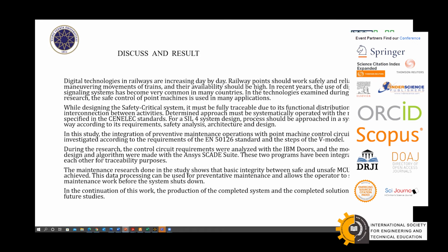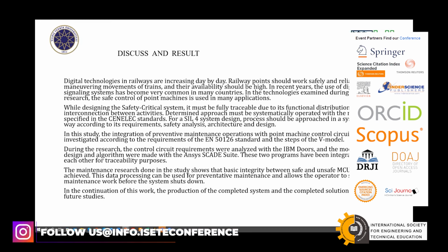The determined approach must be systematically operated with the methods specified in the CENELEC standard. For a SIL4 system design, the process should be approached in a systematic way according to its requirements, safety analysis, architecture, and design. In this study, the integration of preventative maintenance operations with point machine control circuits has been investigated according to the requirements of the EN 50126 standard and the steps of the V model. During the research, the control circuit requirements were analyzed with IBM DOORS, and the model-based design and algorithm were made with ANSYS SCADE. These two programs have been integrated with each other for traceability purposes.